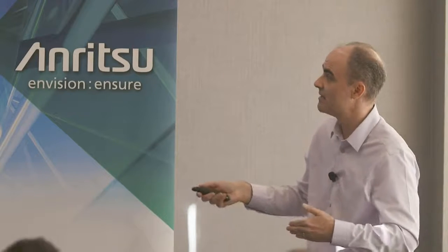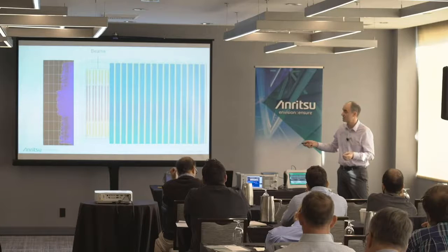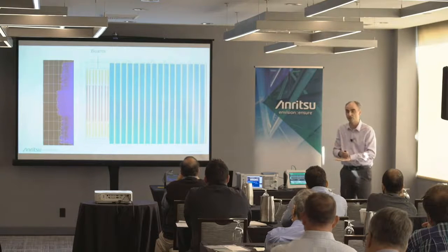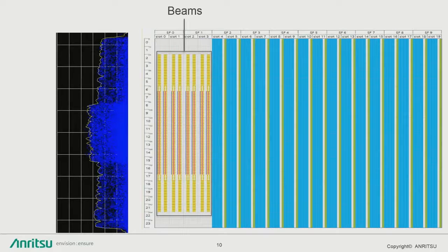But a real-time spectrum analyzer will grab the entire chunk and process it at the same time. So sweeping kind of goes away. I mean, it technically still does some sweeping, but essentially it grabs that whole piece, processes that data at the same time so that there's no gaps in coverage. Okay? That's important because a swept spectrum analyzer may sweep across this when this is not present, and therefore the signal's not there, it doesn't show up. A real-time spectrum analyzer, like you see here, will grab all of this data and be able to display it in a persistence display. Okay? Therefore, because this happens very regularly, and this may not occur as often, you get the different density and the different signal strengths out here. So when you're looking at a spectrum analyzer on a 5G signal, that's why you see what you see. Okay?